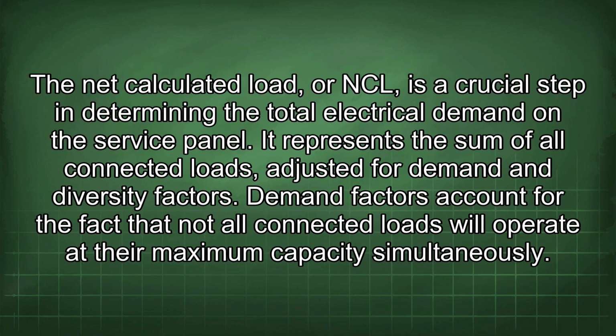The net calculated load, or NCL, is a crucial step in determining the total electrical demand on the service panel. It represents the sum of all connected loads adjusted for demand and diversity factors. Demand factors account for the fact that not all connected loads will operate at their maximum capacity simultaneously.